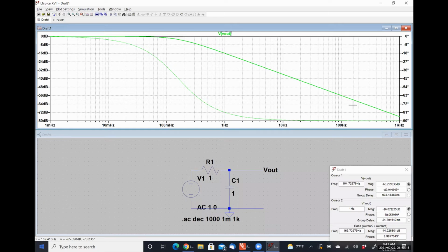-60 dB means that our signal has 1,000 times less signal power than it started with. So that's why we consider that effectively 0. If you ever go work for a government facility designing electromagnetic shielding or anything like that, that's what they're usually looking for: 60 decibels of attenuation as a minimum, because that means whatever you put in, less than 1,000th comes out.